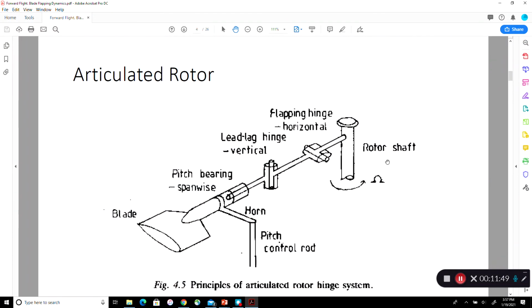In the main rotor, this is a fully articulated rotor. This has got lots of moving parts. Remember, each one is a hinge, like your door hinge. You don't want to have a lot of friction. You don't want to get dirt in there. You are operating in the sandstorm, Operation Desert Storm. So there's a lot of inspection, cleaning, and lubricating. Each one of these hinges, each one of these bearings needs to be inspected. So there's a lot of maintenance there.